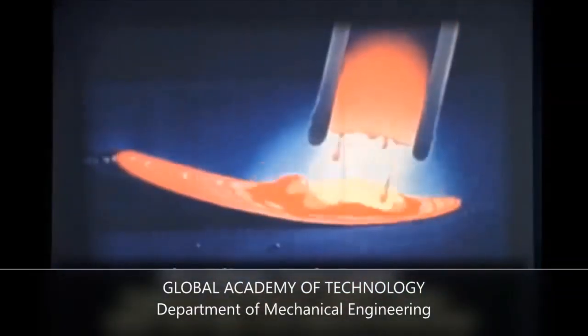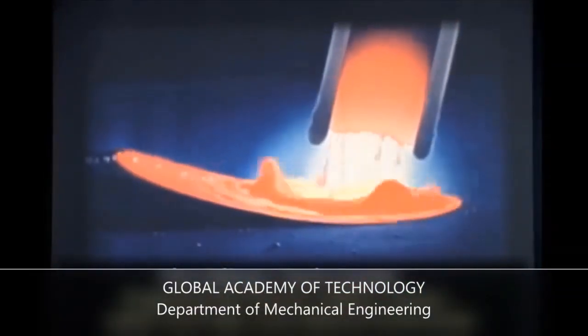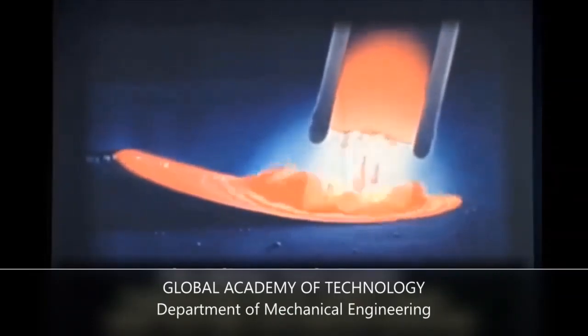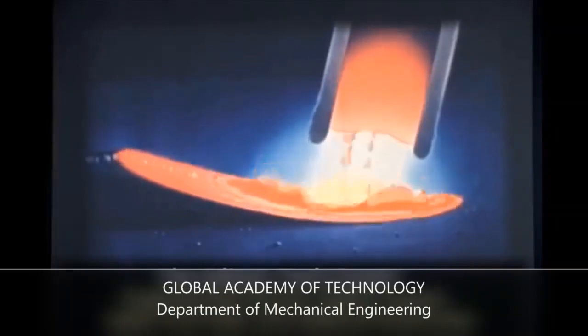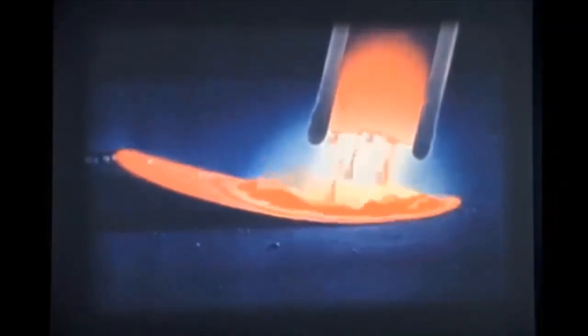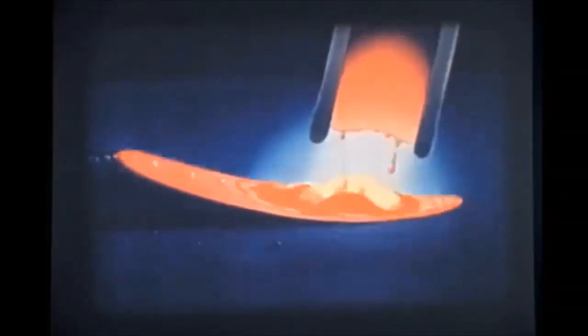At the same time that the metal is melting, the coating on the electrode is being consumed. This takes place slower than the melting of the electrode, which shields the arc and helps direct the flow of metal. It also permits the use of higher currents, with the resultant faster deposit of weld metal.